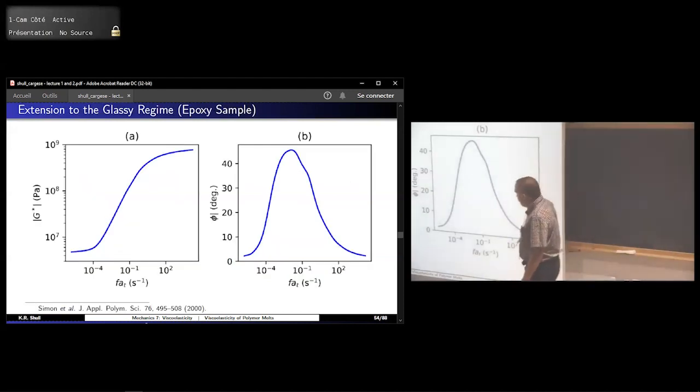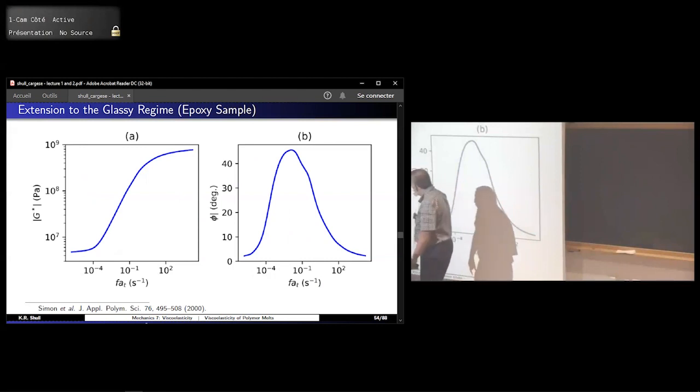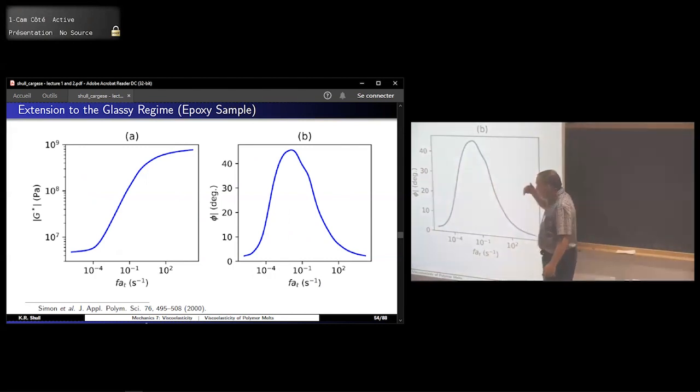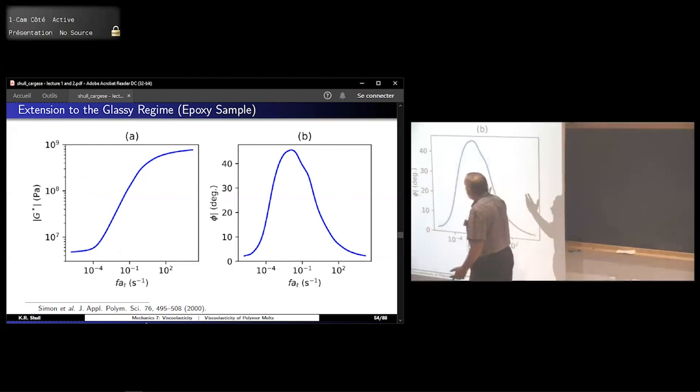This I actually found from the literature. It's tough to find nice literature data that you can plot yourself. But in this 20-year-old paper down here at the bottom, for an epoxy material, they give a 20-element fit, so 20 different exponentials. You just add them up and you can plot it however you want. So that, in this case, is what this modulus looks like.